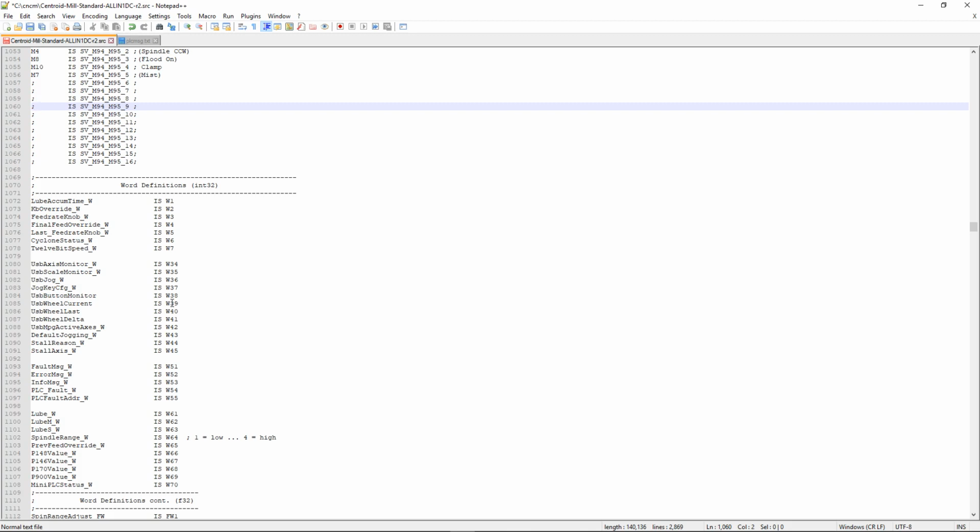What you could do is, depending on the tool changer, the timing between how long it takes for the carousel to come in between one and the other might vary. Maybe there's a longer arm on one as opposed to the other. So rather than having a constant definition in the PLC program, and therefore having two different PLC programs for the different machines, you can have it parameter based, where you set a parameter based on the amount of time that you want.